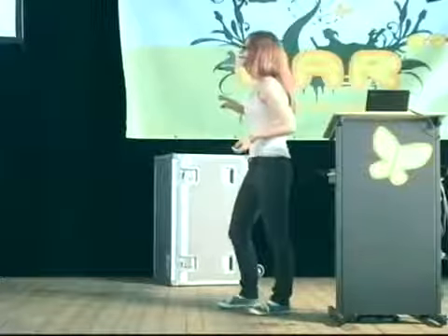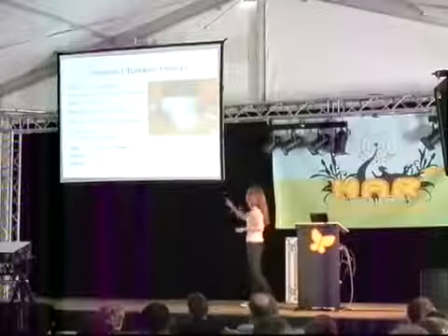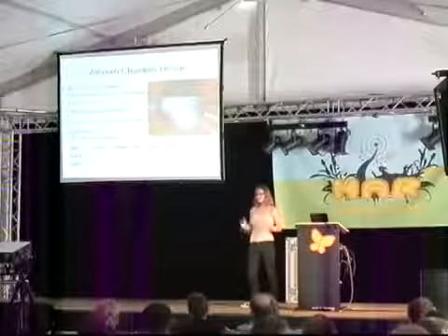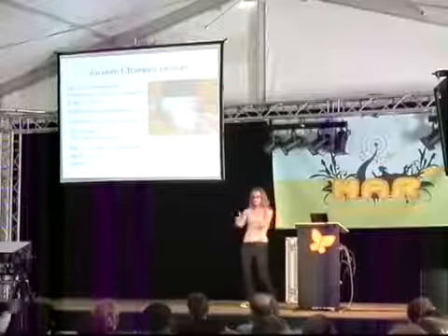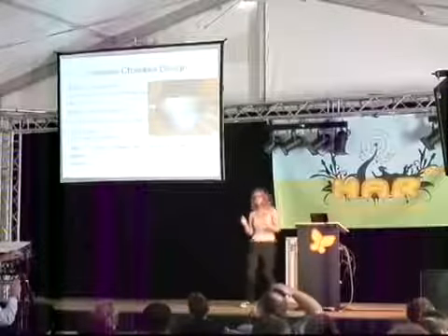Now, two types of aluminum that are good to be aware of. I'm not sure how much people know about these types of aluminum, but 6061 is the cheapest type of aluminum. It's standard. It's very easy to machine. I use this for the body of the cyclotron because that can have thicker walls, so it's not under as significant stress. Top and bottom lids, it's better to use aircraft grade aluminum, 7075. That's really, really annoying to machine, but you can make it smaller, so you'll be able to fit the cyclotron inside a tighter gap, which is useful, depending on the type of magnet you're able to buy or make.